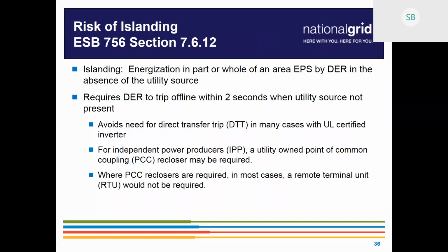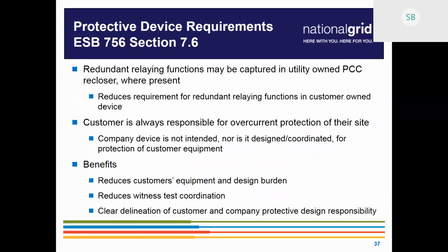And in the next slide, when you say that you need overcurrent protection, would that require a recloser anyway? Not in all cases, so that's where it would kind of be up to you. If you feel that you could protect your site with fuses, and we were able to move our redundant relay elements into the PCC recloser, then that's fine with us.